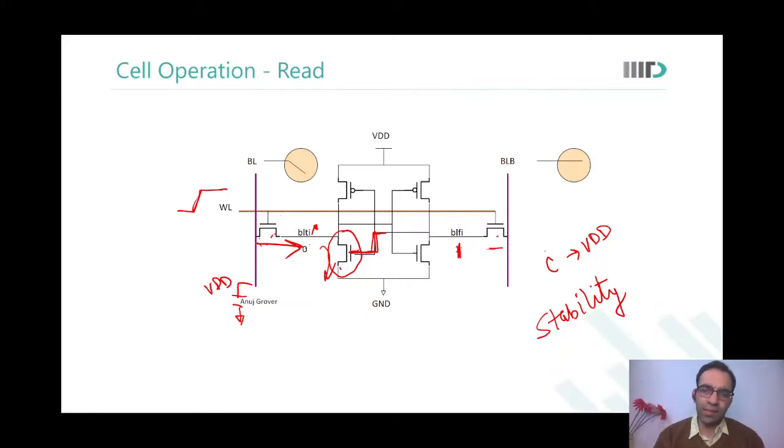So we had that SAN horizontal wire in the IO region, na? Sir, I mean, I showed that. So is that wire coming from somewhere around here? How can it come from every memory cell? Oh, yes. We talked about the reference bit cell and reference bit lines and reference word lines, na? Yes, sir. That was exactly for this purpose. So that we could generate the enable signal for the sense amplifier. Okay. We'll look at that in more detail later also. Don't worry. Yes, sir.